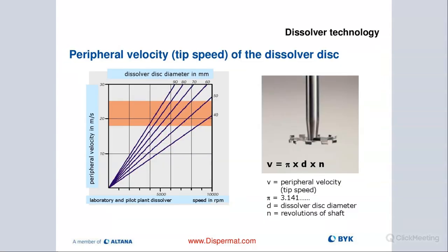No, that's the calculation here of the tip speed. But depending on how your product is formulated, you can make these adjustments to the blade. So I always start out with about 1/3 diameter, and then you see the movement inside of the container. If you're looking at a nice donut, then you know you have probably selected the right blade. If it's too thick, then you may want to increase the blade size. If it's thinner, then you want to reduce the blade diameter.